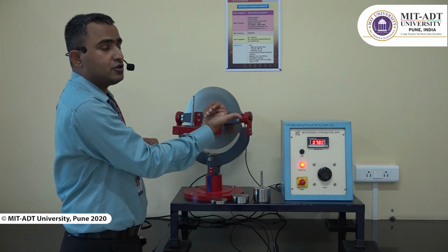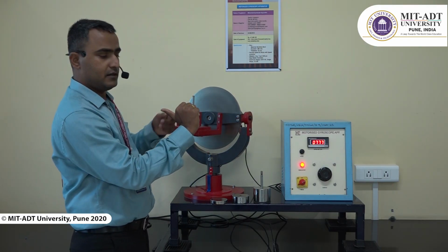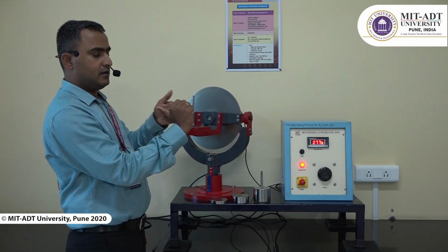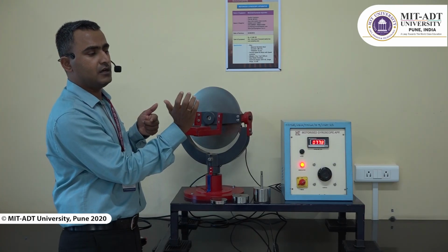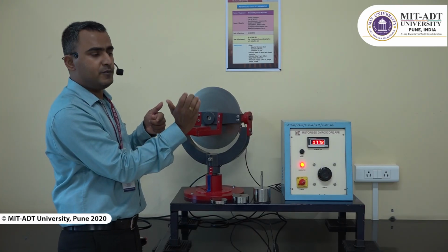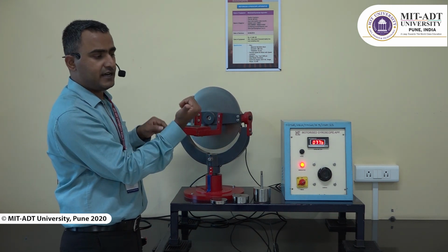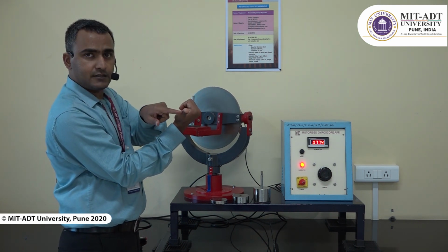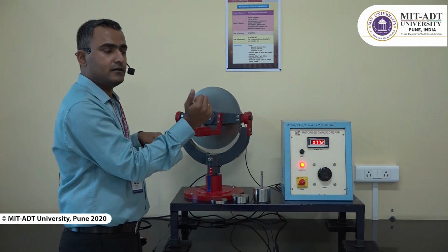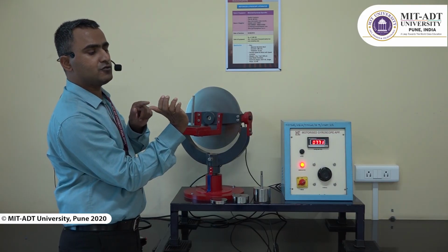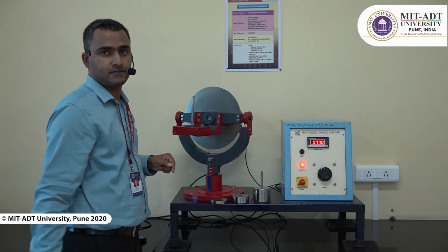So this is the position of active gyroscopic couple. And exactly opposite to that, towards me, is the reactive gyroscopic couple. And what does the finger show? The axis of spin should be moving towards the upward direction. So that's why when I try to push this axis of spin in this way, it is also going upward, because the reactive gyroscopic couple is pushing the axis of spin in upward direction.